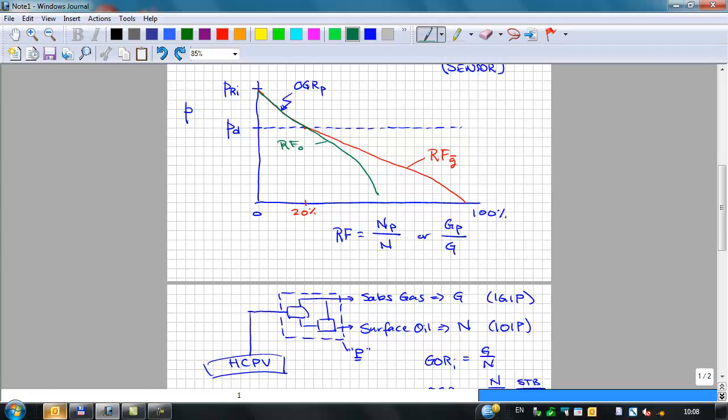No, heat is fixed here. The K values need to be high. The K values of the heavy component, C7. To vaporize C7, you want the K value of C7 to be as high as possible, because it's saying that component prefers to be more and more in the vapor phase. We go to low pressures, we get high K values, and the K value is inversely proportional to pressure.